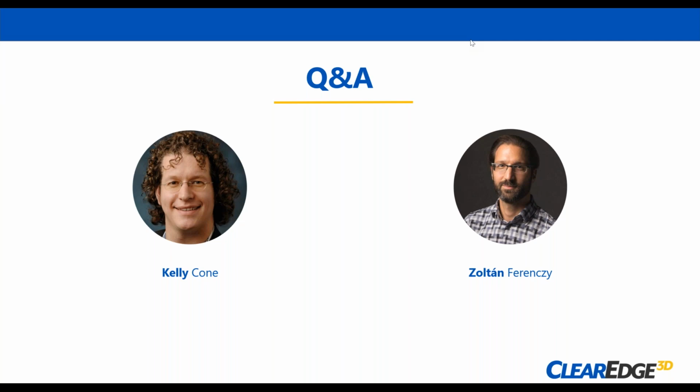John Zahn asked, does that mean you would have to do each scan separately? And so the answer to that, John, is no. We recommend that you register. If you're doing multiple scans, we recommend that you register them together. That's generally part of the typical process, and that you bring all those scans in. So what you saw on Zoltan's screen is actually, I think, 2 or 3 scan positions all registered together. So we were looking at 2 or 3 scans and analyzing them all together.